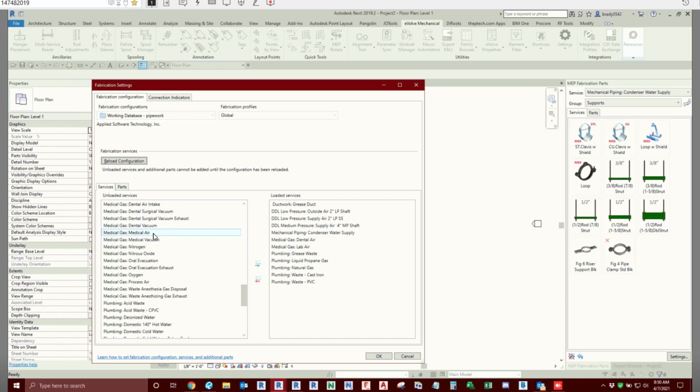Let me load a domestic water. I'm looking for domestic water that is less conservative, called UPC, which is Uniform Plumbing Code. And even those rod sizes and hanger spacings are different. So this is a lot more complicated on the piping side than it is on the sheet metal side. But be aware that this is important when you go to set your tables.